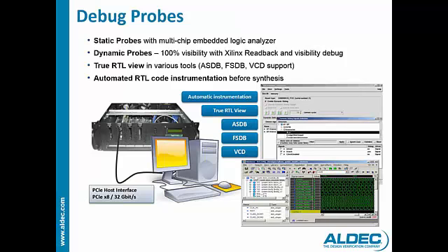These are signals identified before synthesis and captured during emulation in an embedded logic analyzer, something similar to Xilinx ChipScope. Then there are dynamic probes, which use the Xilinx readback tool to capture the state of the design, and the hardware debugging algorithm expands these to full visibility.